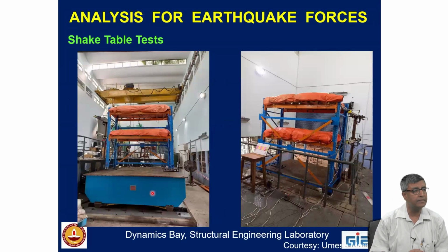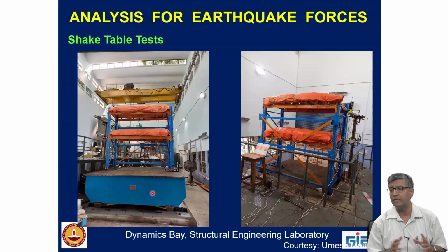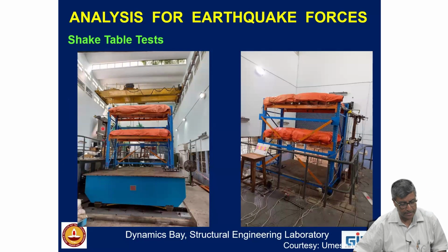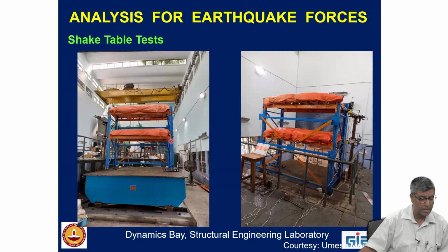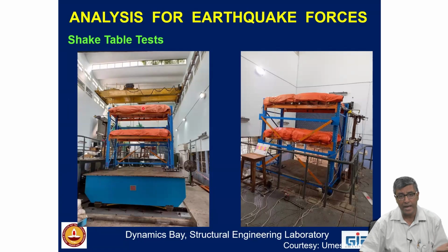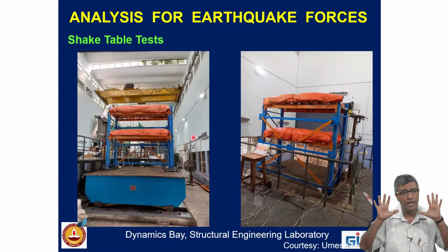Now, today you will be seeing this in our lab. We have a small scale shake table, but good enough for our research purpose. Here you can see a specimen for storage racks. And here you can see that the masses have been provided to simulate certain inertial effect. And here the base will be moved and not the force applied. Just adjacent to it, you will be seeing the reaction wall, which is used for what are called quasi-static tests. There we are not shaking the base, we are applying the force horizontally.